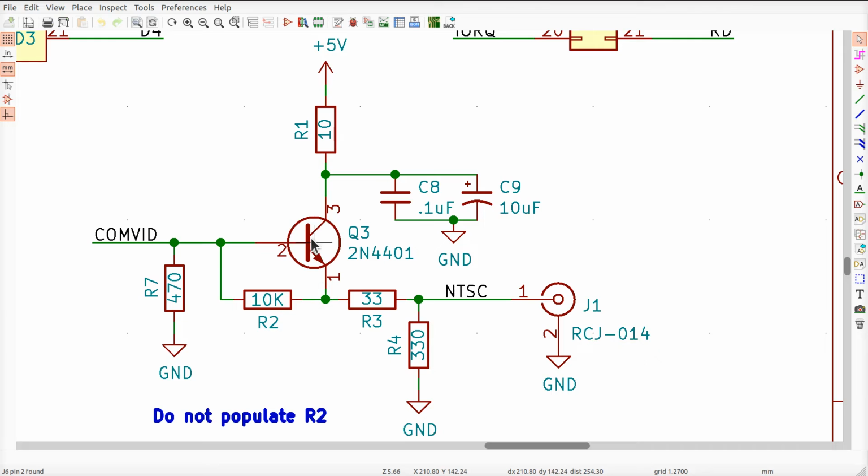It has to go up to 1 volt or maybe 2 volts over here before it's divided out to 1.5 volts or something like that, and be terminated into these low resistances over here, the 75 over there. So this can't be too big. Otherwise, this voltage will never get up high enough. In other words, the bigger one you put here, the more you have to tinker around with these over there, and it may not work. So you could either put a small resistance like this in here, or a ferrite bead, or an inductor, or something like that.